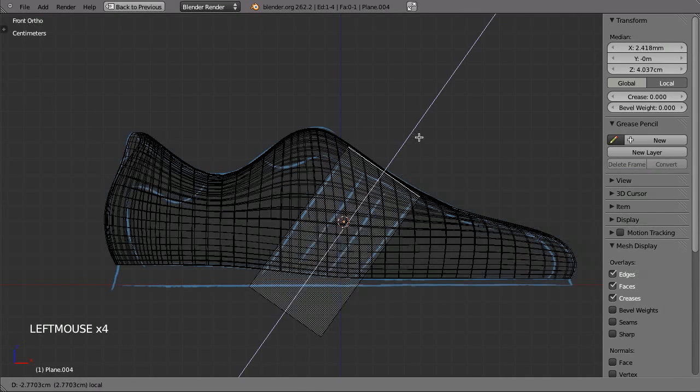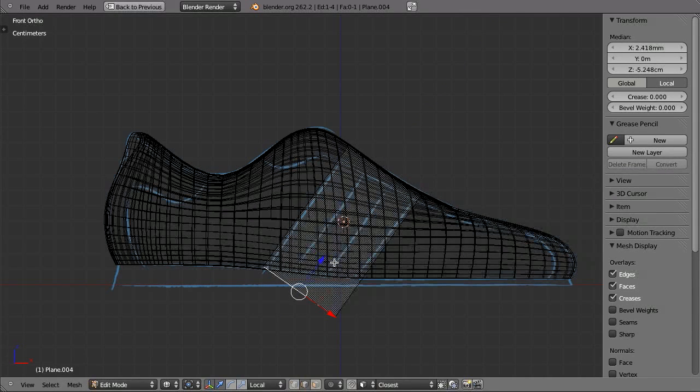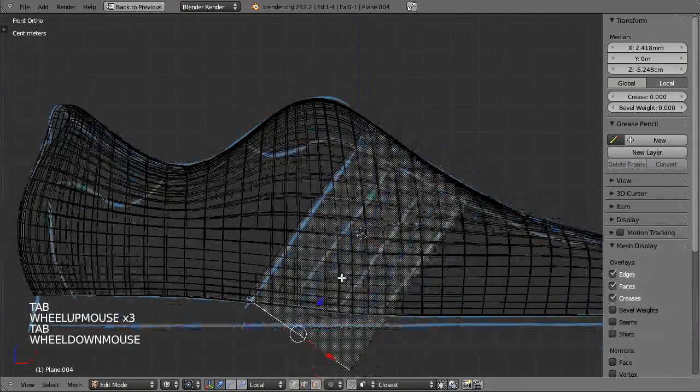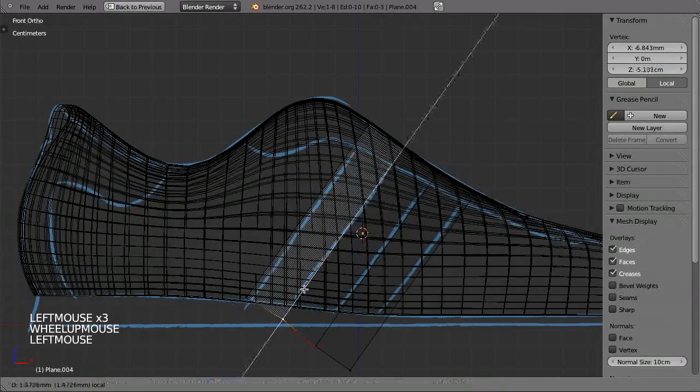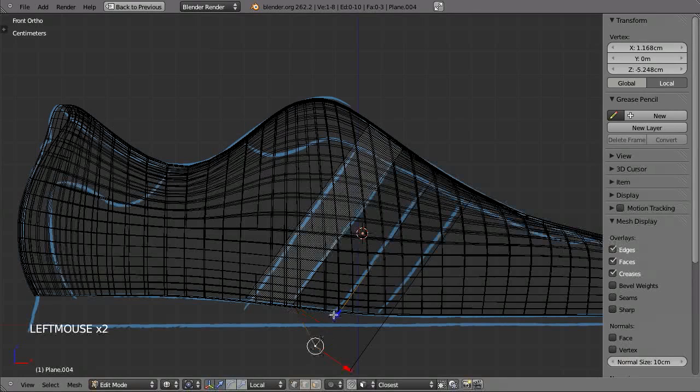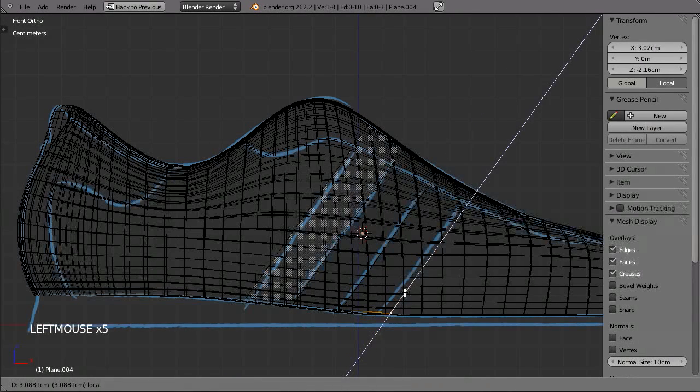So now you can see when I select this edge, I can comfortably just reposition it like this. And this way, it's easier to just move those points along the direction I really need instead of just straight up or down. So I'm going to add 2 loop cuts because I would like the lower points to line up with the lower edge of my shoe.